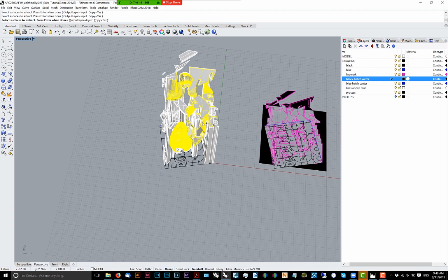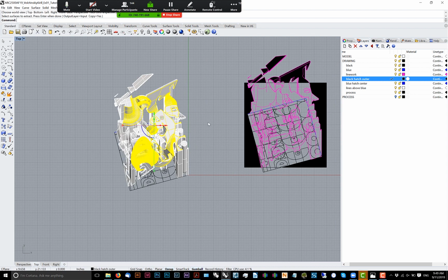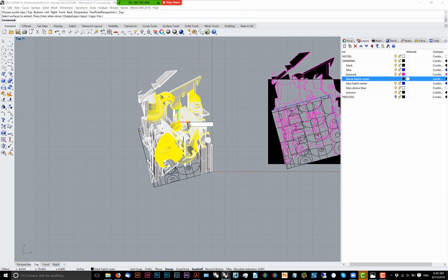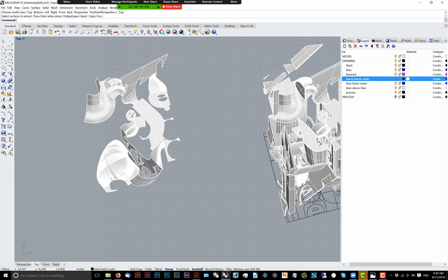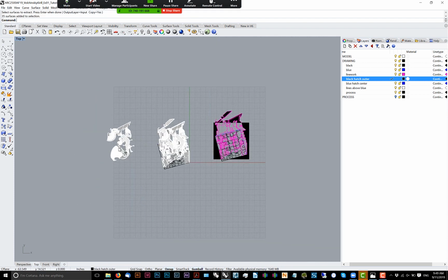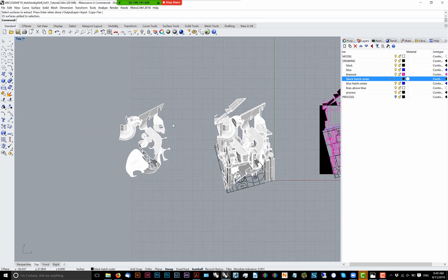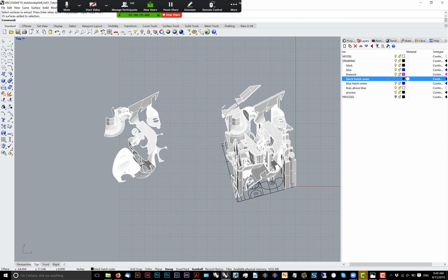So now that we basically highlighted the shapes that you want to give more visual presence to in your actual drawing, we'll run the extract surface command, and we'll translate them over, just using the move command or the gumball tool. So then you end up with these shapes. Now it's a question of how do you bring them back into your graphic. So one idea is we'll actually be using these shapes to project information onto, and that will help render the curvature a little bit more effectively.